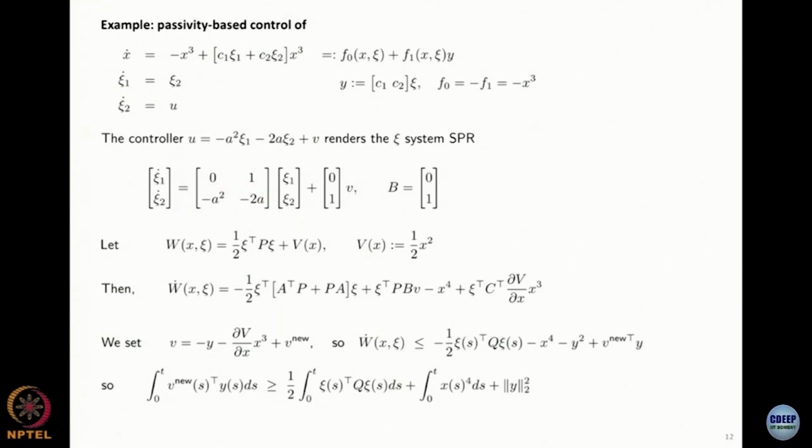So let's say we choose these control gains to make the system down here asymptotically stable, and you add an extra input, as I said, to take care of these guys here. Okay, so this is the matrix that we saw before. So here A is just 0, 1, 0, 0, right? And this guy here is A minus BK, yeah? Which I made Hurwitz. Then there is the extra input.